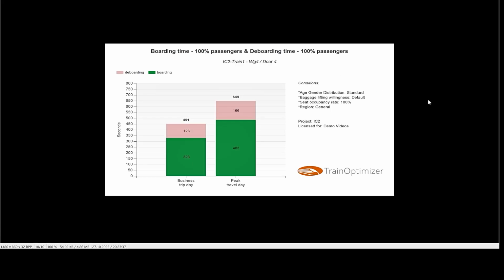For the overall and total presentation, it makes sense to repeat the evaluation with different values for passengers boarding and alighting. You can either specify concrete numbers, for example, 40 people, 50 people, or a utilization value below 100% to calculate the passenger changeover time. A 100% utilization means that all passengers alight and the same number board again.